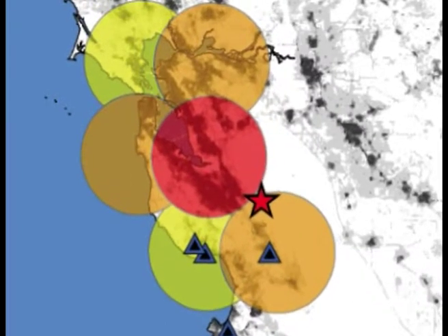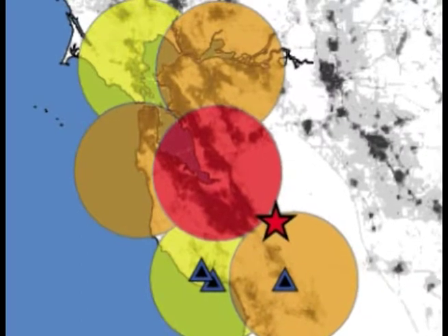Presentation of such logs for all shot points in record section form allows mapping of velocity, which with proper well ties can be converted into a lithological cross section comparable to that which would be obtained from closely spaced boreholes. Such presentations give valuable information on stratigraphy in areas where conditions are favorable.